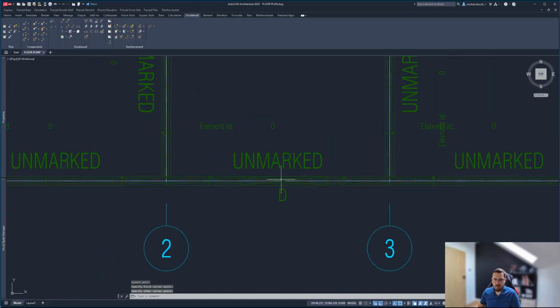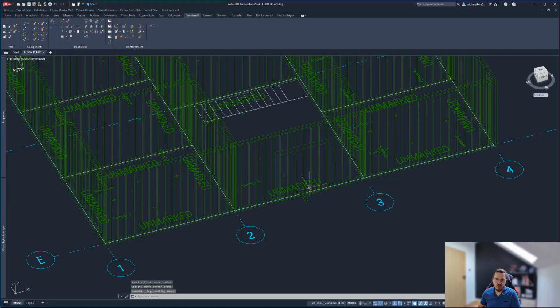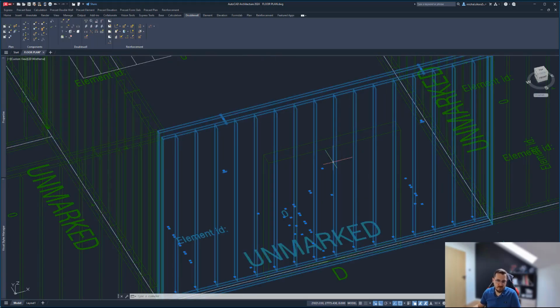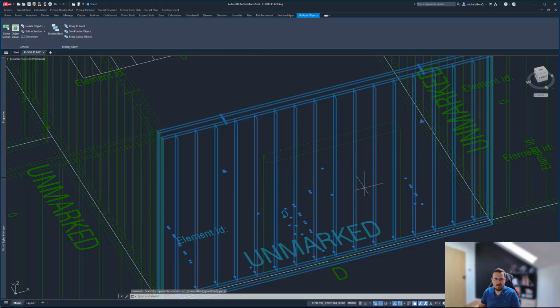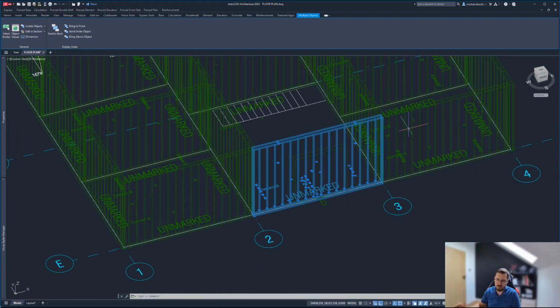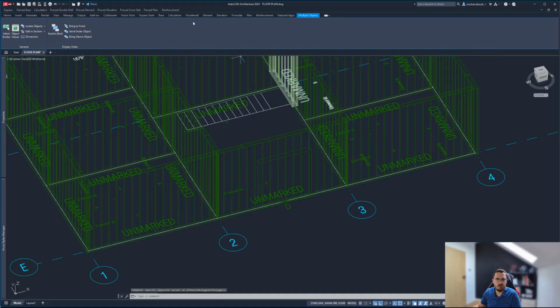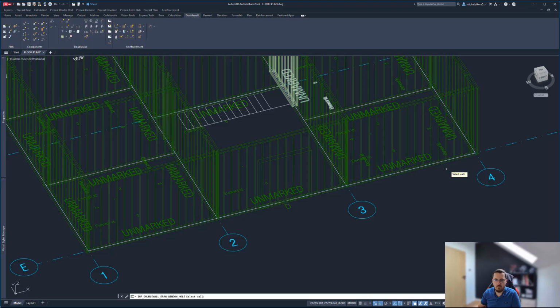And see, here we have an opening. If I rotate that, be advised that it doesn't immediately refresh the element that the opening is in. So the girders have not been cut yet. When we reopen the model, or when we actually create drawings, they will be automatically cut. There you will have the girders cut. Same thing if we go for the window openings.